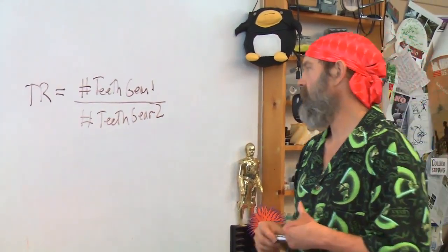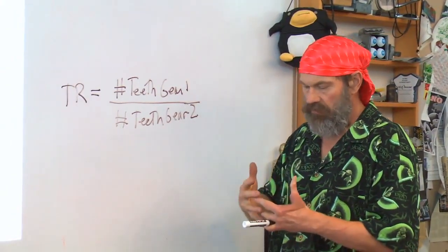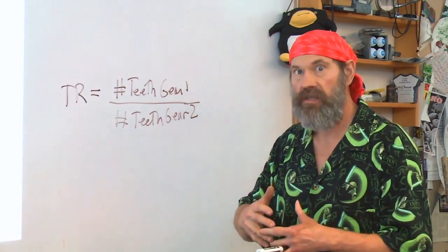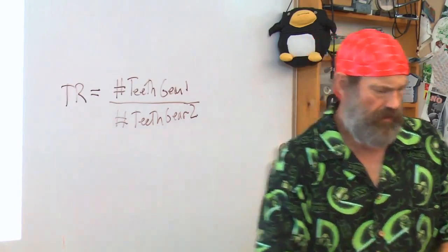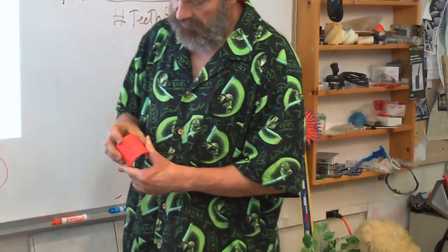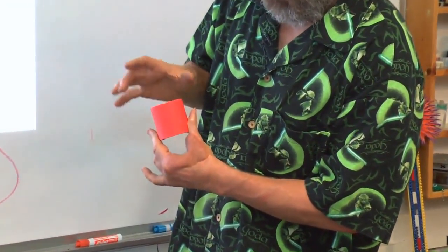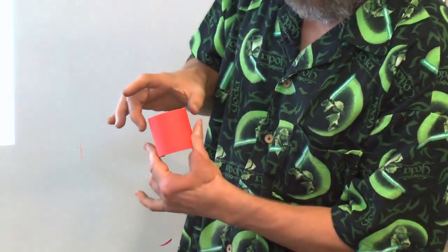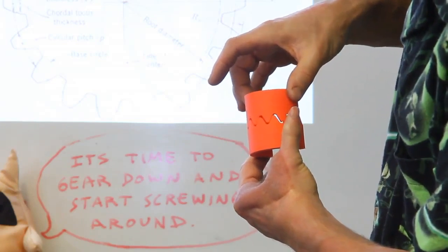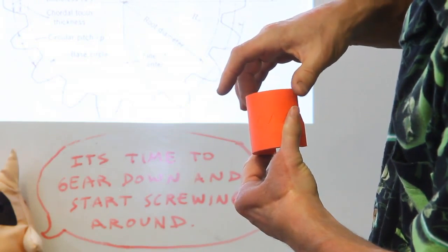Now, how big the teeth are has a huge effect on the torque that can be transmitted through the shafts, the quietness of the gear engagement, and how the mounting has to occur. And I have this. These would be what would be called face gears, but this is a nice demo here because they're really big, chunky teeth. When you apply torque or twist, watch what happens. See the way the one moves relative to another, this one slides up the other?